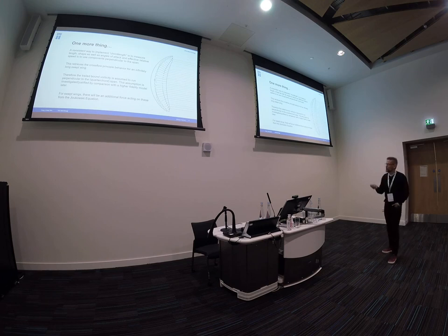Let's say you have a wing like this with a lot of sweep. Then there's one more free parameter, because now I say that from a cross-flow principle, you always use directions perpendicular to the span, and I define the span like the quarter chord, because that's where the action point of the force is usually allocated.